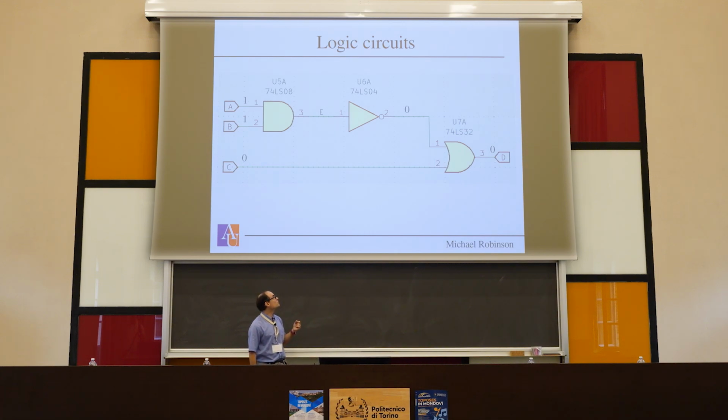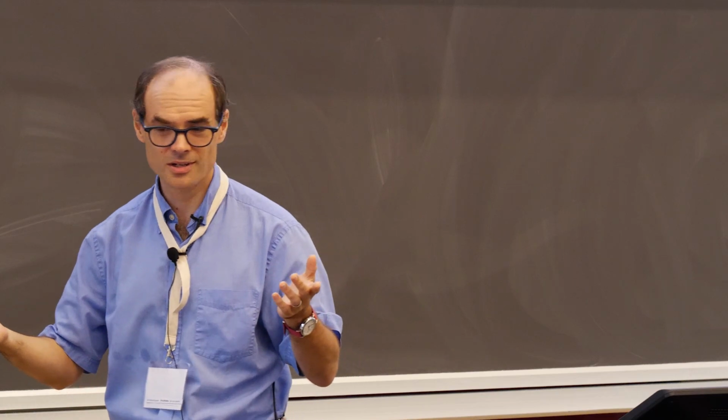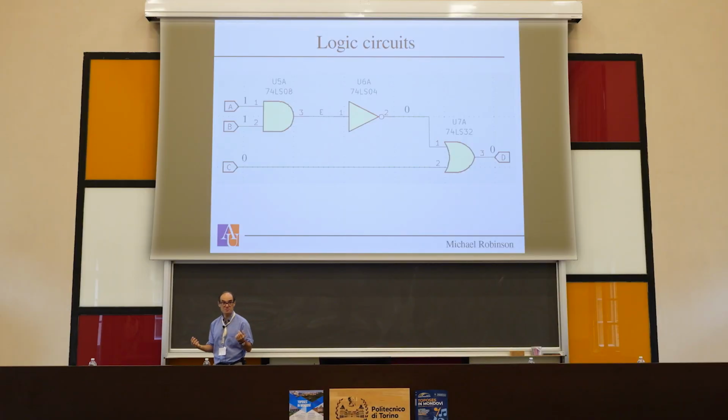It's also worth noting you can do various kinds of stupid tricks with these. You could take a NOT gate and wire its input back to its output. What does that do? True is false. Is true is what? Contradiction? Actually, what it turns out is that it depends on the technology that you've used to build the circuit. Some of these circuits will oscillate. Some of them will attain some value which is neither true nor false. Some of them will become unstable and will be true or false kind of randomly. Interesting. Anyway, that's an aside.